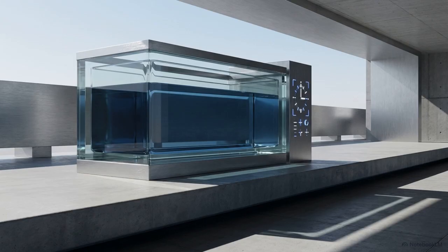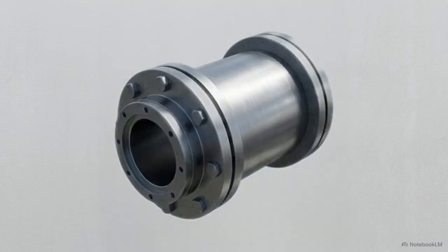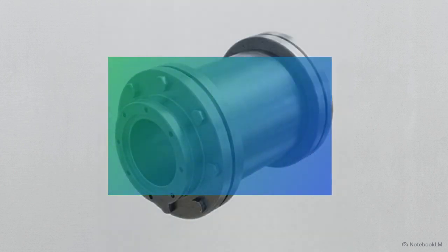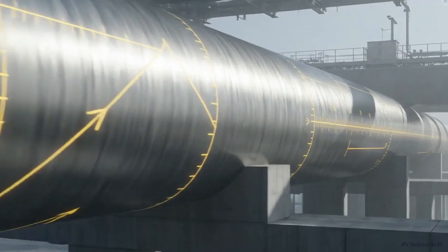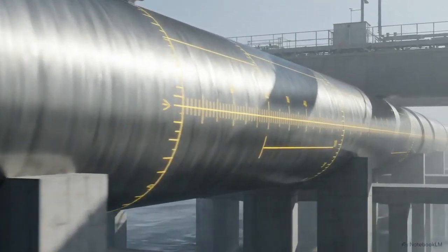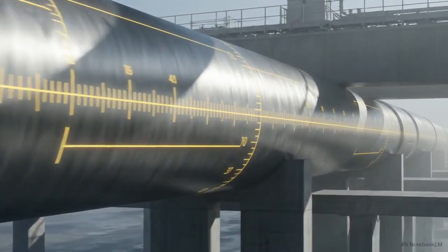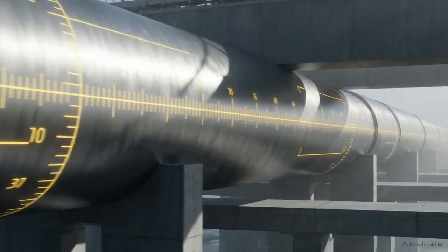In a standard batch reactor, you observe a chemical reaction progress over time within a fixed space. In a PFR, that timeline is stretched out physically. The chemical composition changes as a direct function of distance traveled. By completely eliminating axial backmixing, process engineers can map the exact duration of a chemical reaction directly onto the physical length of a continuous pipe.